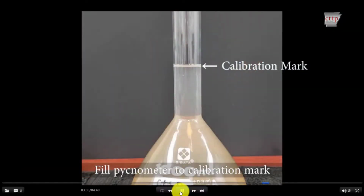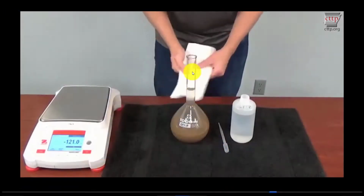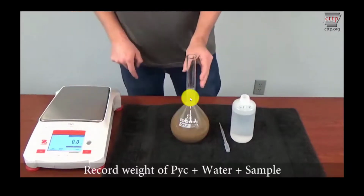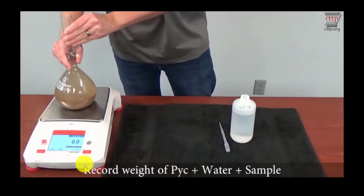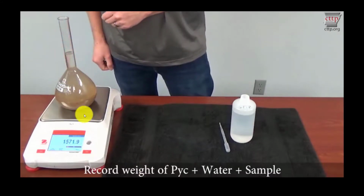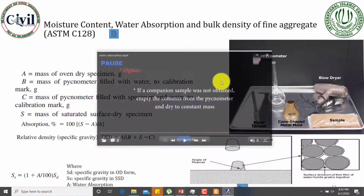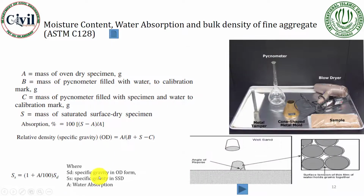You will note the lower meniscus of water at this point and then weigh the specimen. Now clean it as a precautionary measure in order to avoid the excess water attached on it. Then record the weight of pycnometer, water and sand sample in SSD form.